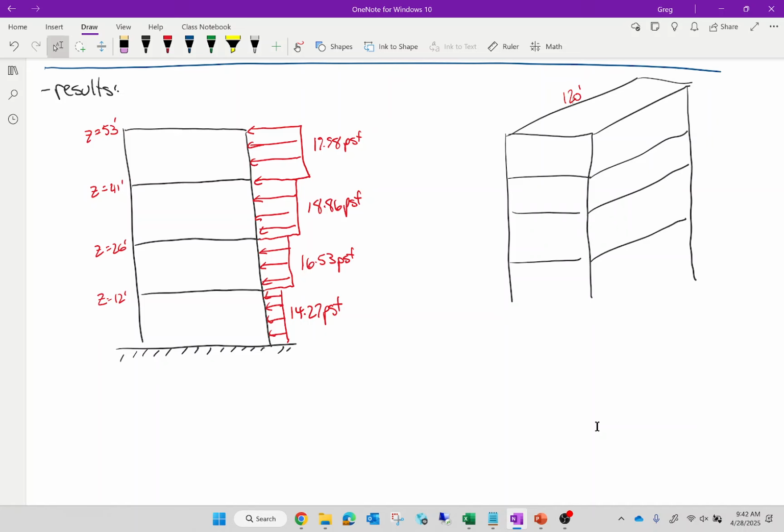That makes sense, right? It really wouldn't make sense to put bracing only on one side. Maybe you'd put them on both sides so that half the wind force goes to this frame, half the wind force goes to this frame, so that they're equally resisting that wind load. Does that make sense? So if I were to treat this frame as an element and this braced frame as an element, would you agree that maybe that point right there is the center or the centroid of these two frames? So I'm going to call this